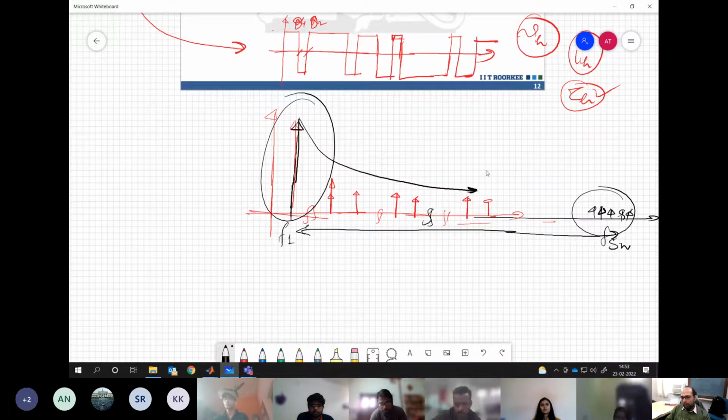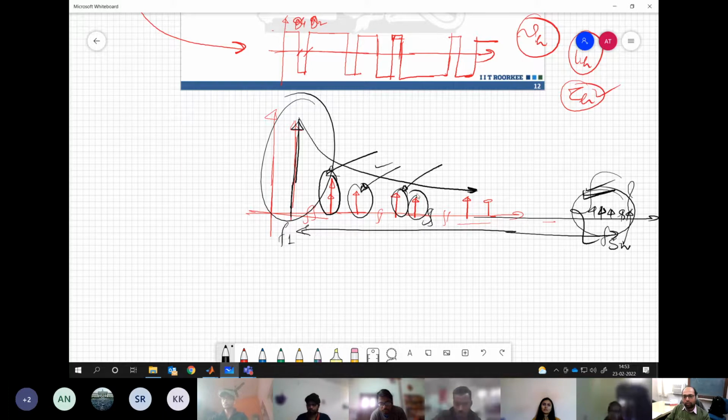So what we need to have, basically, when we are dealing with different systems, is to know whether the individual harmonic is important to be analyzed or it is the set of harmonics that we need to analyze. This difference should be clear. When we are dealing with low switching frequency, these are the dominant components which we need to know.